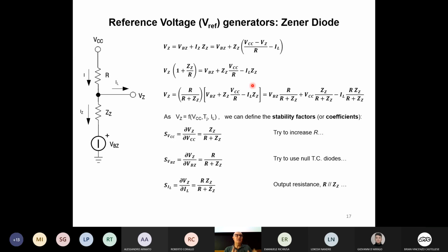So in the dynamic range, the current generator will be open. There will be left only its parasitic dynamic resistance. Remember current mirror circuits. If I use a current mirror circuit, a current generator with a high dynamic resistance, this value will go up to infinite, and the sensitivity will go to 0.